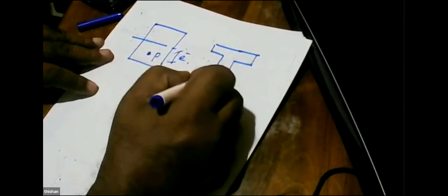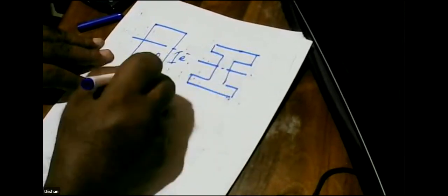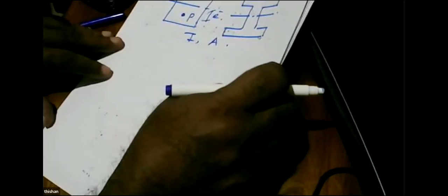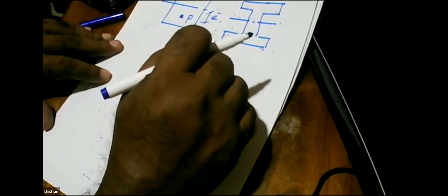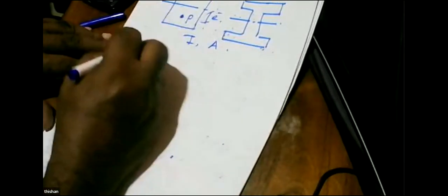So we say subjected to force P, eccentricity e. The shape doesn't matter because we are going to talk in terms of section properties, and the section properties will be I and area. So I is the second moment of area. So we are going to talk in terms of these properties. We are not going to worry too much about the shape because we are going to make use of the properties. Whenever we want this, we need to have a sign convention.